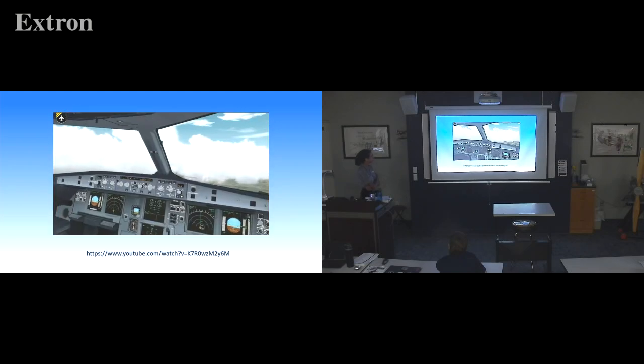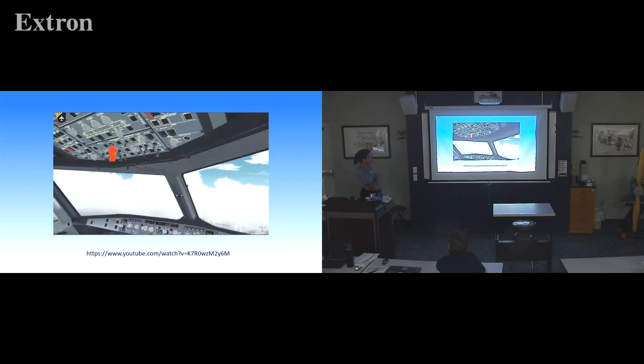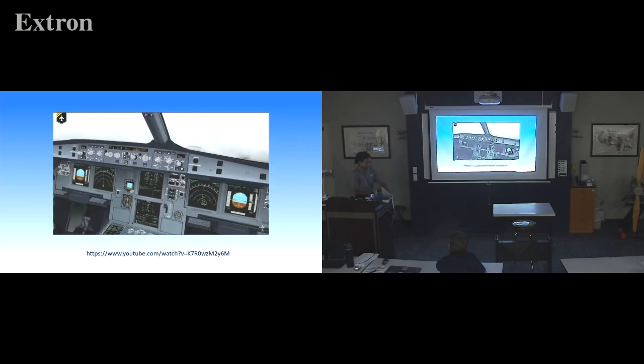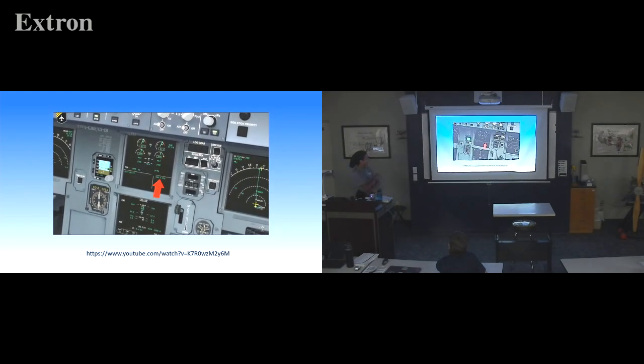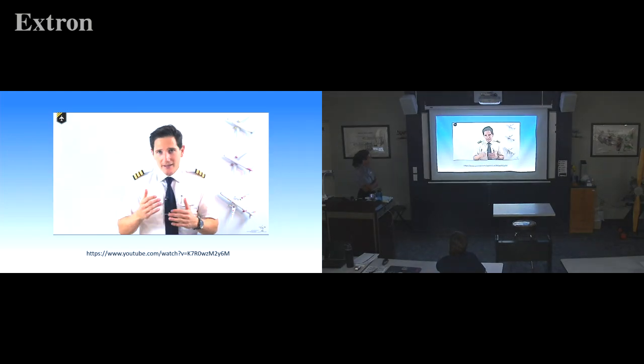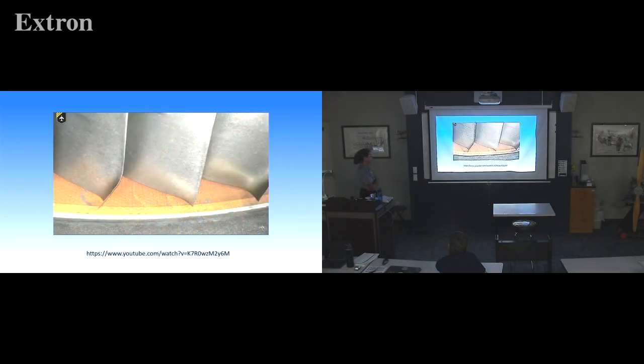And the ECAM displays engine anti-ice, and at the same time the turbine ignition system is set to continuous to prevent any engine flame out should a lot of water be injected. Now you need to take special care in case of rapid ice buildup, because as you press the engine anti-ice button, chunks of ice could get sucked into the engine and damage the fan blades.